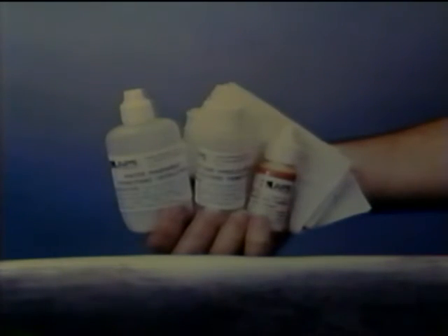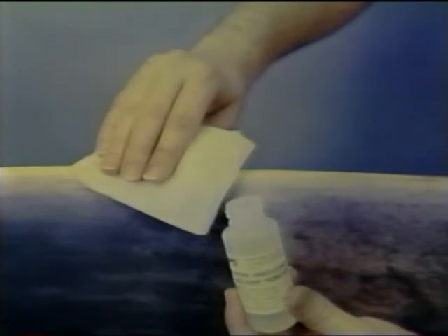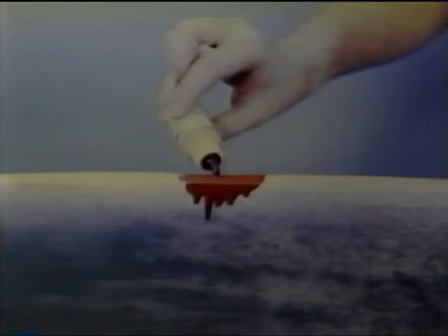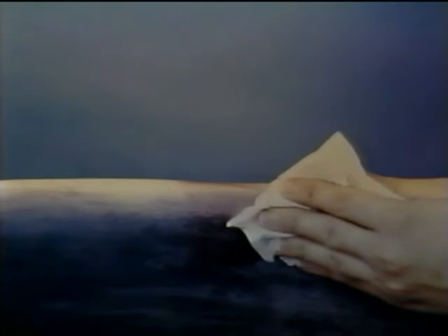In order to determine if all of the damage has been removed and no cracks exist, a simple dye-penetrant inspection may be used. Before applying the penetrant, carefully clean the area to be checked. Use clean solvent and a soft cloth. Apply the penetrant according to the directions and wait the specified dwell time. Remove the penetrant by wiping the blade with a clean, dry cloth. After most of the penetrant has been removed, wipe with a clean cloth moistened with solvent.